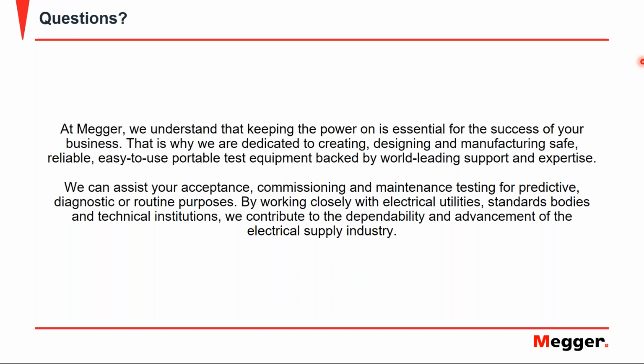It's a good question. I didn't get to cover that example. Obviously I only covered the damped AC example because of my test object. But when performing your VLF cosine rectangular, it depends. One is if you're going to step up in voltage and find that inception voltage. While performing your cosine rectangular test, you can change the voltage. It's not going to be in as discrete steps as damped AC, because it's going to be a continuous output, but you can increase your voltage and decrease the same way.